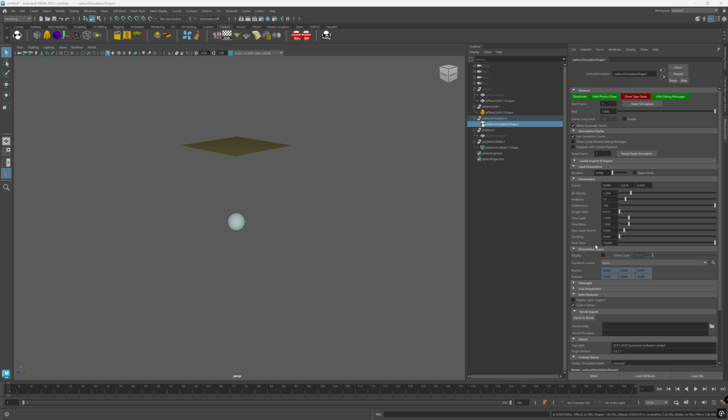Panic time is the valid simulation subdivision time threshold in seconds. If a subdivision takes longer to simulate, then the simulation is interrupted. So it allows you to recover the session in case of heavy geometry corruption as an alternative to the escape key. You can set it to 0 to completely disable it, or just use a very large number as a safety buffer. Let me show you what this means in practice.